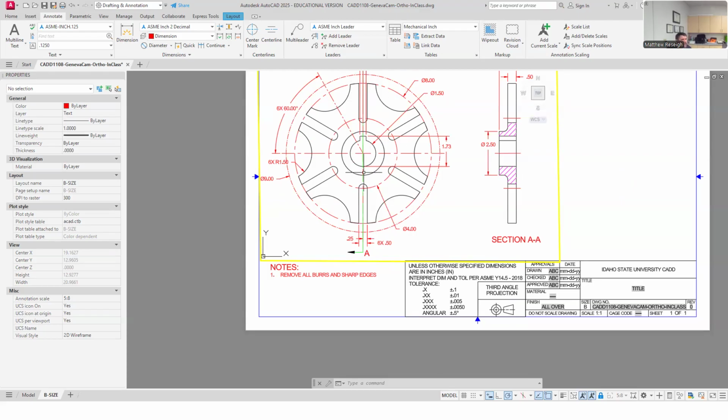So however you're dimensioning it, just think of where that pattern begins, and is where it begins a good control point? And it's not just out there in space off of another feature. It's not dimensioned from feature to feature, but from control point to feature. Yeah. Good. It makes me think.